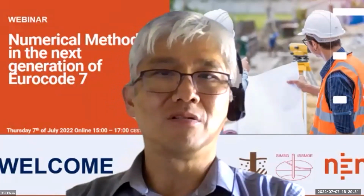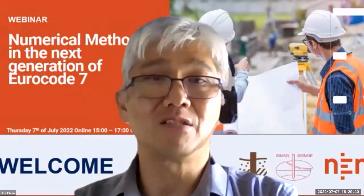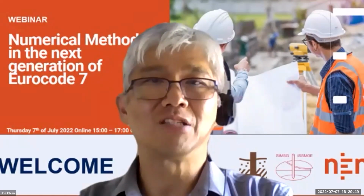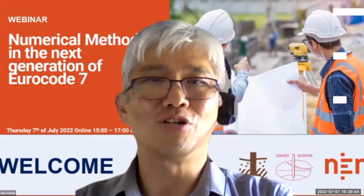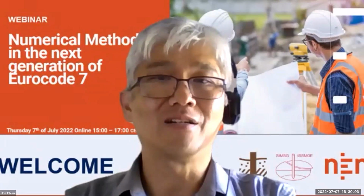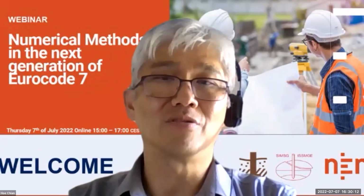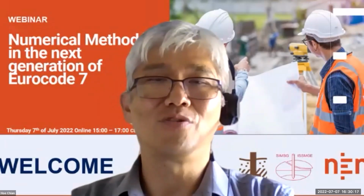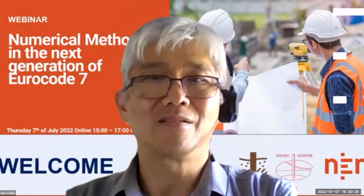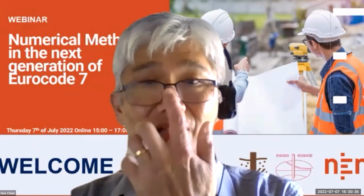If you have a model to run under combination 3, so-called verification case 3, and you want to run the phi-C reduction, you can. The only problem is the one that I highlighted there. If you have layered soil with drained and undrained soil input, CU and phi-C, then where do you stop the phi-C reduction? Some software allows you to set a partial factor that stops the computation. But if you've got CU input and you need 1.4, and then phi-C, you need 1.25 on the tangent of phi, then you don't know where to stop. That is what is critical when you do the automated strength reduction approach.